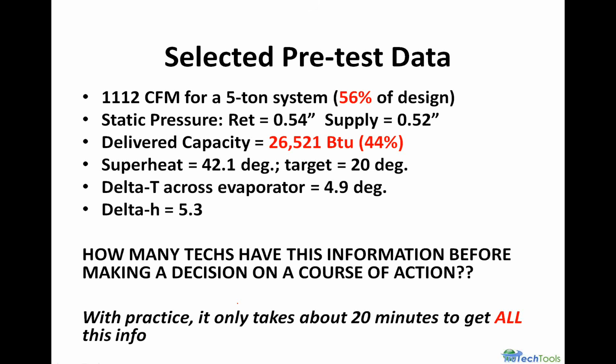What's interesting is, if you really think about it, the only thing extra we're doing is measuring supply air wet bulb and dry bulb. We have to measure return air wet bulb and dry bulb to charge. We have to measure airflow to make sure the system's right. Once the airflow is measured, it doesn't change. So that's a given. And so we measured the airflow. We throw 2 wet bulb thermometers in, and we're not taking any more time than we should to properly commission a system.